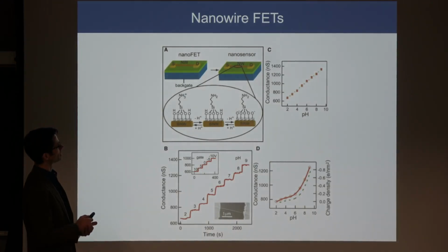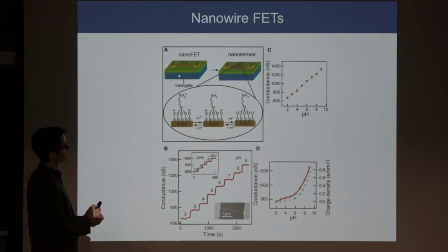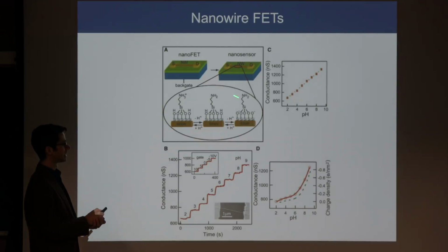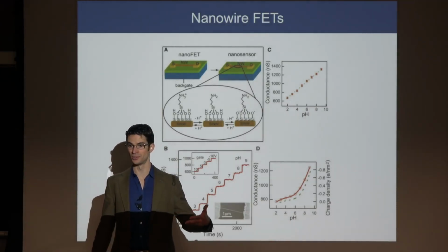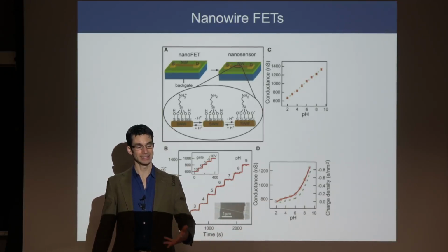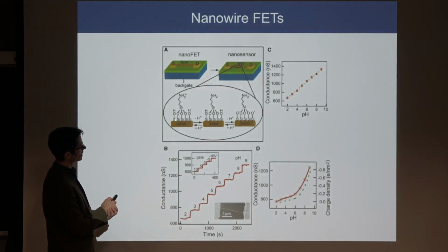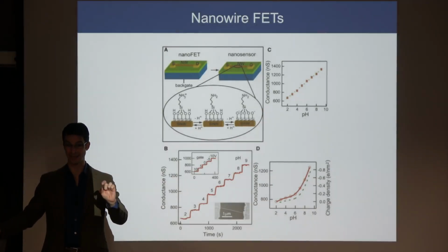And what they did was they took this nanowire and evaporated a source and drain contact on a back gate. The back gate is just this highly doped silicon wafer. And then the green is the dielectric layer. Then they converted this nanowire FET into a nanosensor by chemically modifying it with this amine terminated group. Now, what do we know about amines is that they're sensitive to acid. So if you add acid, the amines will protonate because the amines are a base, right? So if you have a silicon nanowire, silicon in the laboratory environment always has an oxide skin on it.